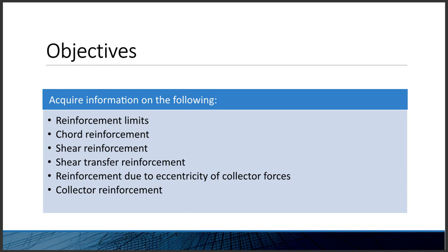We'll look at how to determine the chord reinforcement, shear reinforcement, the shear transfer reinforcement, and then some specialty reinforcement if you have a collector that's wider than the member that it's framing into. And finally, we'll look into our collector reinforcement. So after this particular part, we'll have the complete design for a diaphragm.